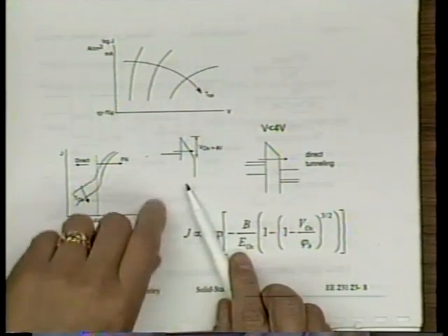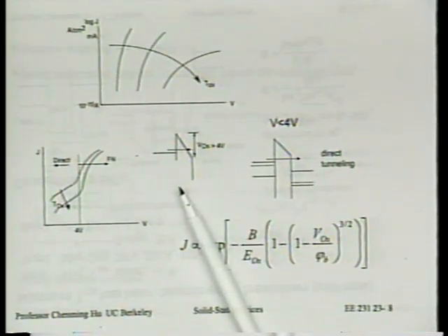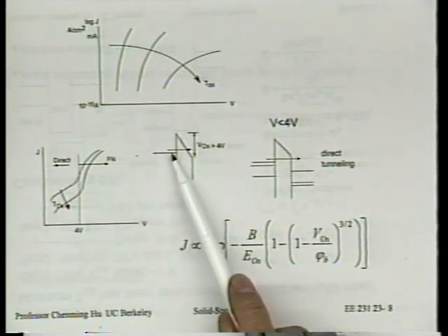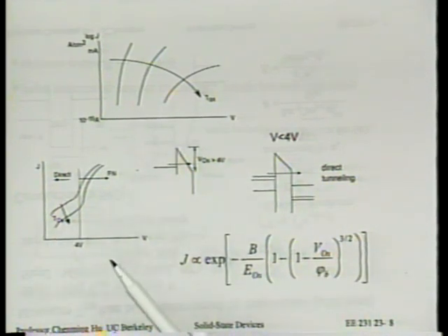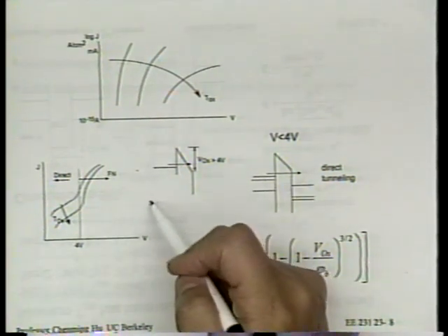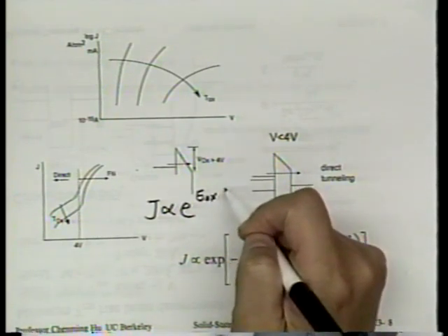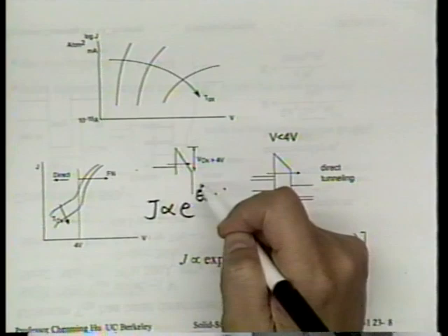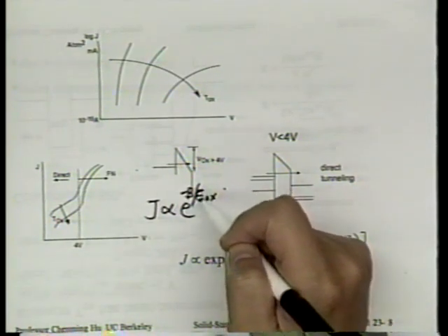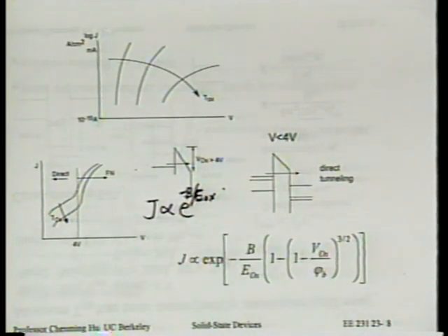And particularly, I'd like you to look at this little diagram here, and this is what we call the condition for Fowler-Nordheim tunneling, sometimes called just FN for short. And the important thing is that the tunneling barrier has a triangular shape. Under this condition, we actually know a particular relationship for that tunneling current. It happens to be an exponential function of this EOX. Some constant divided by EOX, all right? Minus B over EOX. That is the relationship between the tunneling current and the oxide field, okay?